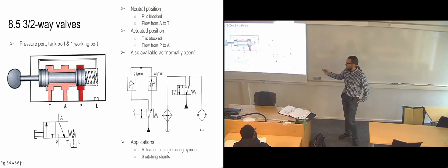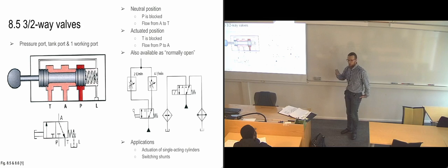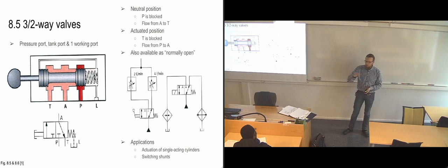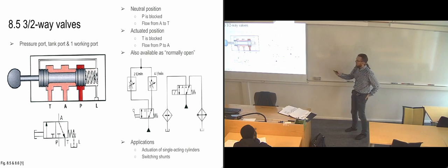Here you have it solenoid operated, so the solenoid is probably connected to a temperature sensor, which reads off the temperature of the hydraulic fluid in the tank, most likely. Then it's going to start switching between cooling and heating, just to keep it at a very constant temperature at all times. So you're also just switching back and forth between 2 different flows in it.